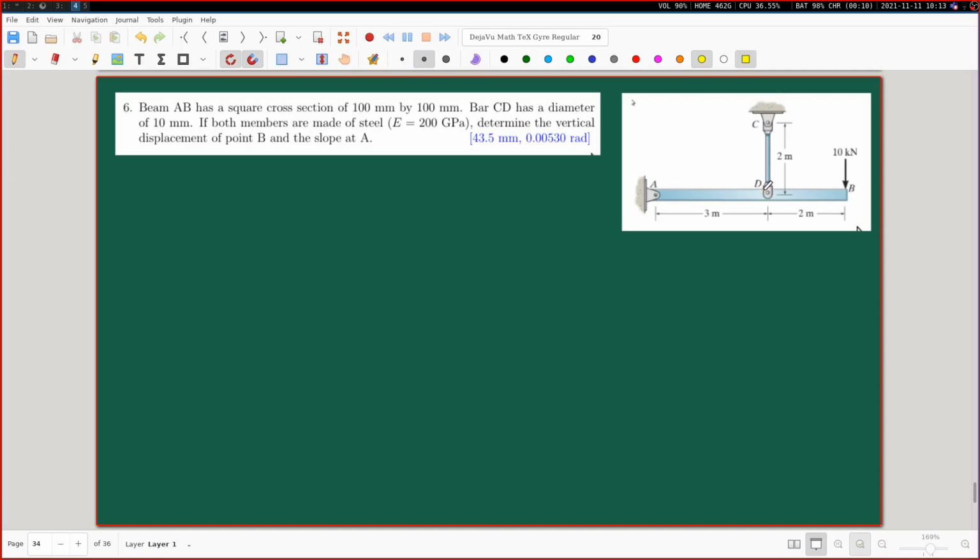If you want to be very formal, the best way actually to ensure that a structure is indeed statically determinate or indeterminate is to actually identify the unknowns, the number of the unknowns, and compare that with the number of static equilibrium equations, which are of course going to be always 3 in number. 3 in number in the sense that we are always going to have not more than 3 independent equations from the considerations of static equilibrium.